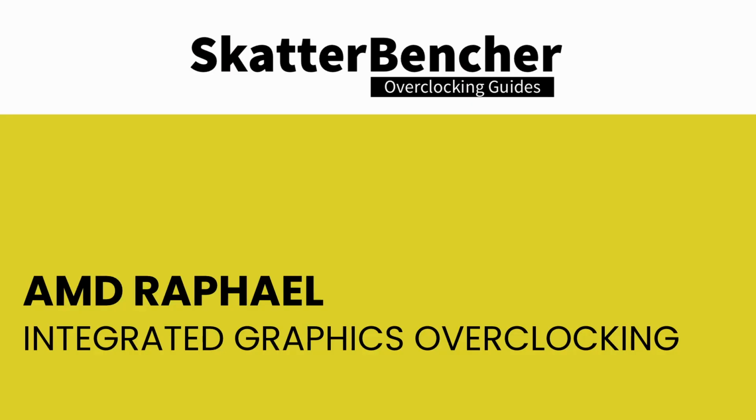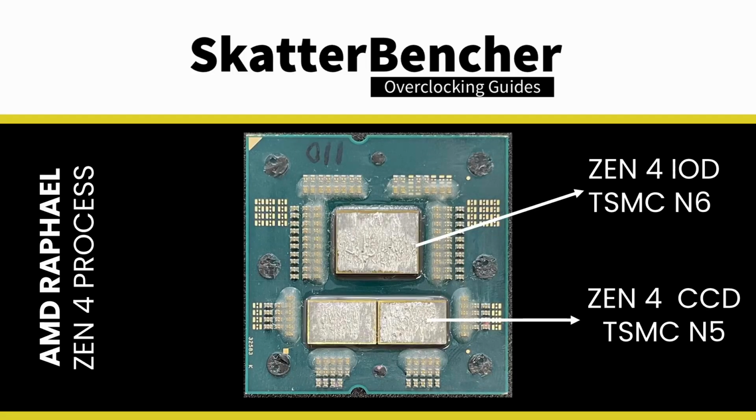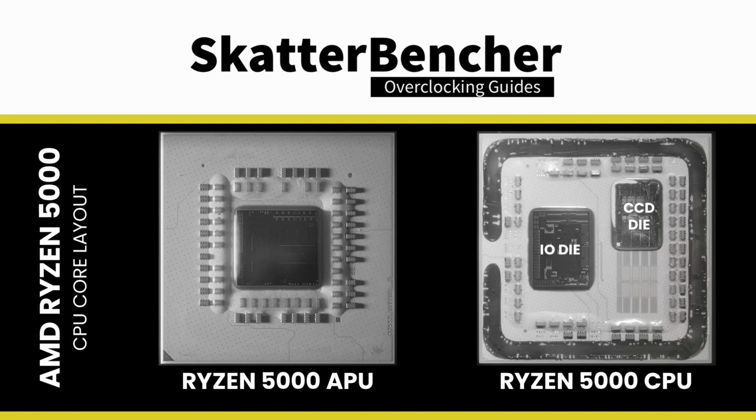Brand new on AMD Raphael is that there's now integrated graphics on an AMD CPU. While that would technically, I guess, make it an APU, AMD still distinguishes between APU and CPU. There are a couple of crucial differences with the APUs. First, the graphics cores are integrated into the I/O die. That's a separate chip from the CPU core dies. That's different from the APUs, where everything is integrated into a single die.